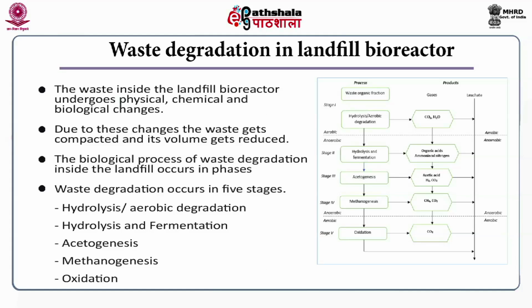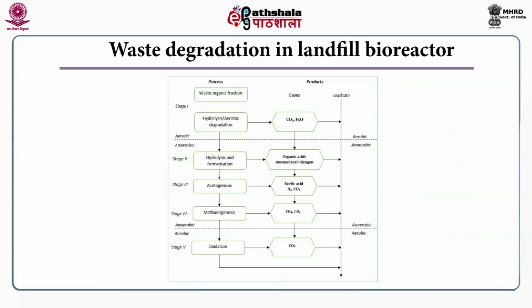We have discussed this in the previous module also, where I told you about the different steps that take place in waste degradation within the landfill, starting from hydrolysis, aerobic degradation, then again hydrolysis and fermentation, then acidogenesis followed by methanogenesis, and final oxidation. The flow chart will give you the different processes that take place inside the landfill bioreactor for waste degradation, and the different products that are produced at the end of each phase.